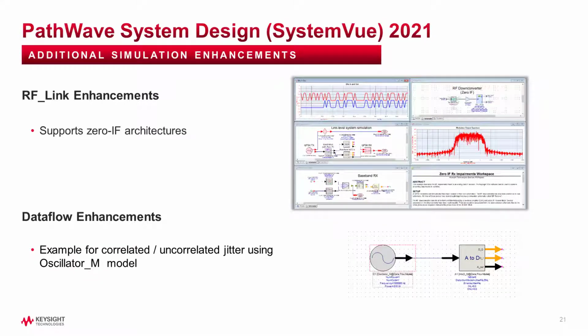We continue to improve the RF Link cross-domain simulator, which connects RF modeling in Spectrasys with data flow. Updates in this release allow users to simulate zero IF architectures and compute link budget and noise performance all the way to baseband.